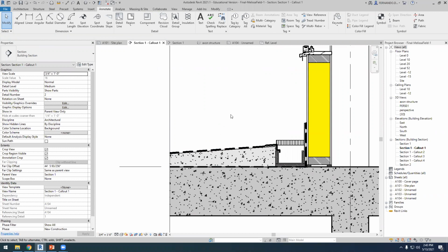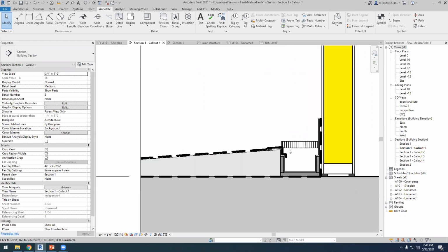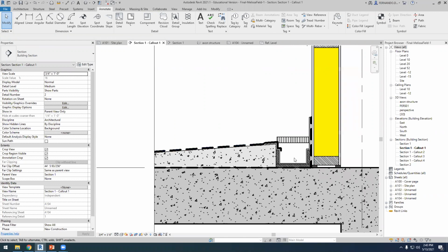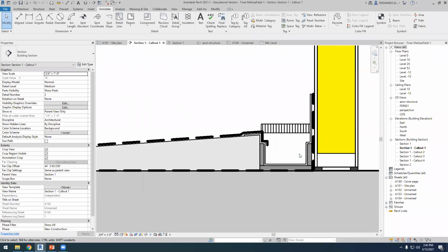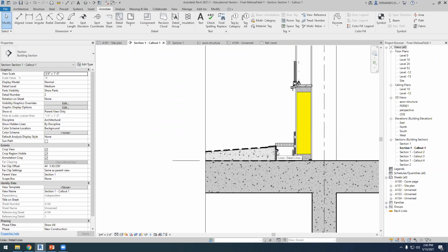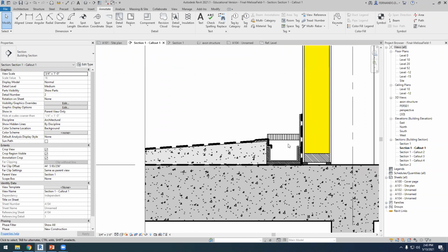In the event that we have water here, first we try to move the water out. If it doesn't work, then we have this gutter to get all the water and get rid of it. And if this is not working, at least we have another waterproof layer here going up so that that wall won't be affected. So we have a 3 level or 3 protection level. I think it's more than, well, it's never more than enough when it comes to water, but I think it's not bad.